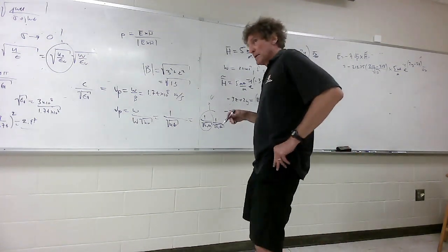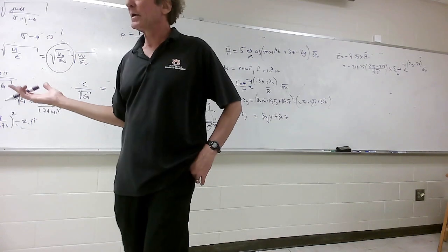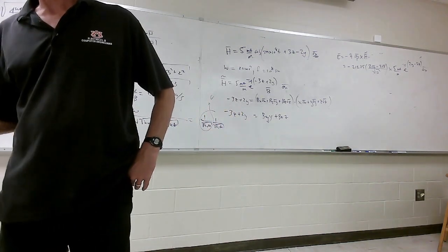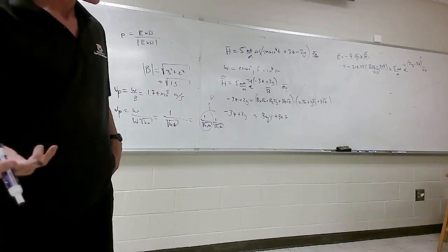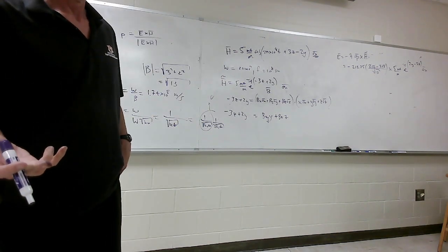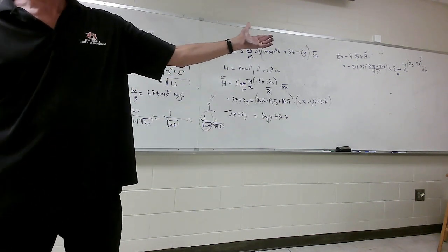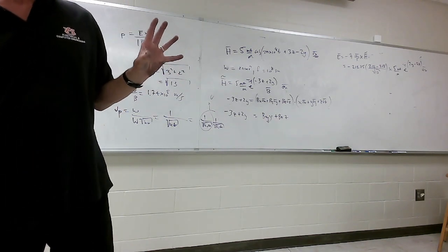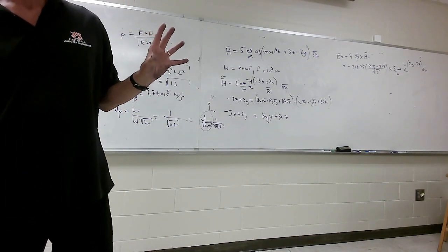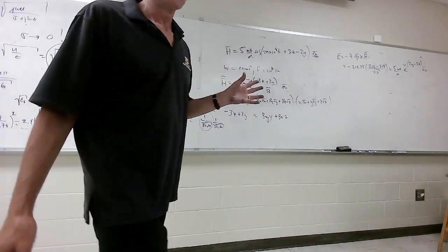This E field's in phasor, correct? Yeah, phasor. If it wasn't phasor, it'd be a cosine of omega t minus something, right? That's time domain. The phasor, there's no time. No, the E field has to be in the phasor. Okay. We're always in phasor until we multiply it by e to the j omega t and then take the real part. Okay. Y'all with me, class? All right, back to this thing.